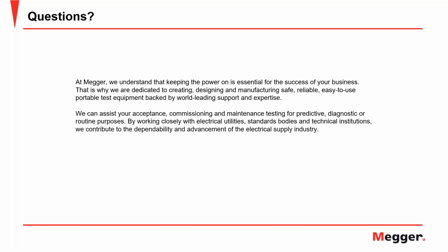We can talk on this question for an hour, but just to give you some idea, whenever you talk about degradation of power factor or capacitance value, you are talking about values increasing. Typically the values would increase, and that would be an indication of insulation being deteriorated or aging.